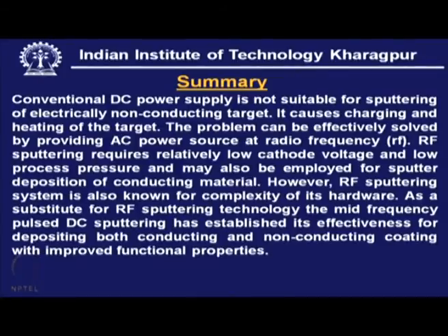As a substitute for this RF sputtering technology, the mid frequency pulse DC sputtering has established its effectiveness for depositing both conducting and non-conducting coatings with improved functional properties.